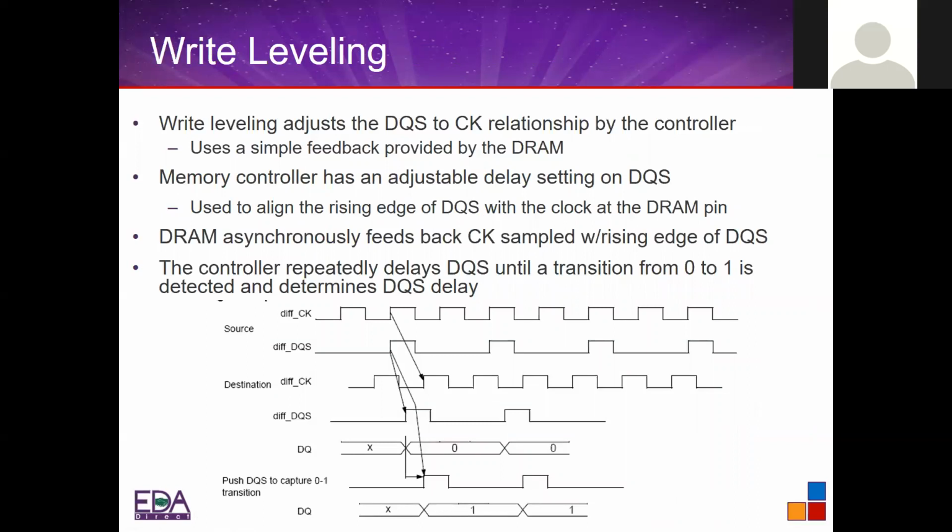And then for DDR structure, sometimes they have this thing called training. And training is basically from the controller sending bits, doing reads and writes to the memory subsystem to determine the delays and to position the strobes. Okay. And once they figure that one out, then those values are programmed into the controller. That's good, but that does not mean that you can be sloppy in your layout. Hey, let the controller take care of this for the variation.